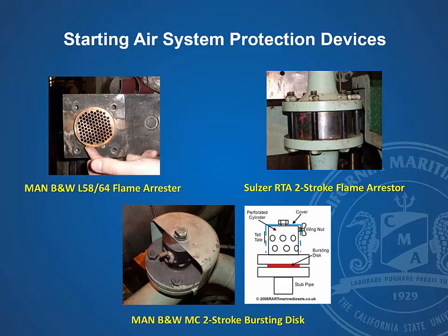So what we're talking about is you have these reciprocating air compressors. They are lubricated by oil. And if that oil was to accumulate in the lines and in the receiver, and you have plenty of oxygen, if you have a flame coming out of the cylinder and into the interior of the piping, which can happen during a start sequence, then that can ignite and explode. So it's a very limited amount of fuel, only what little bit is accumulated, but if it was to burst a line, it can have very dire consequences.